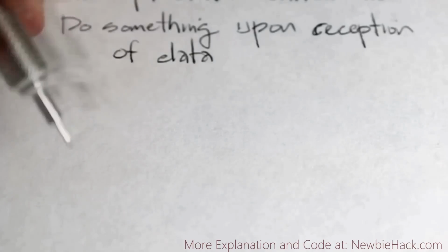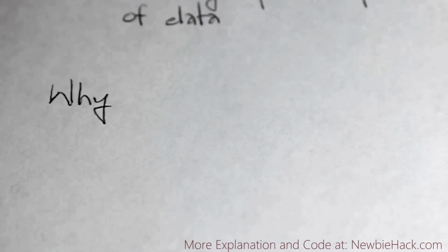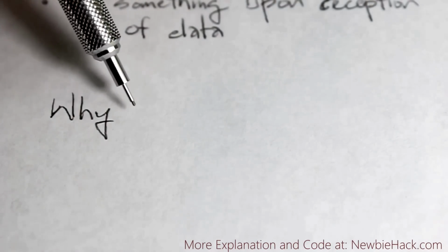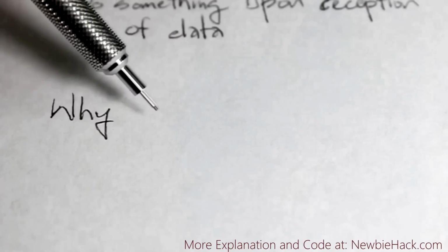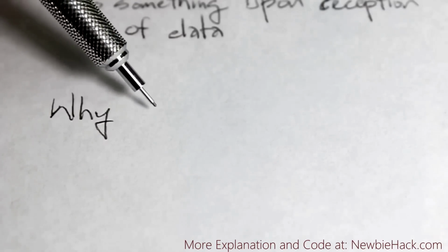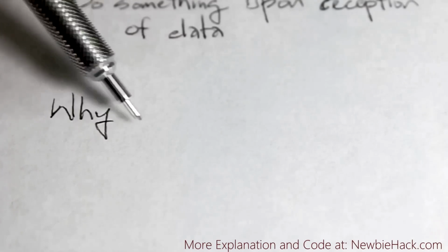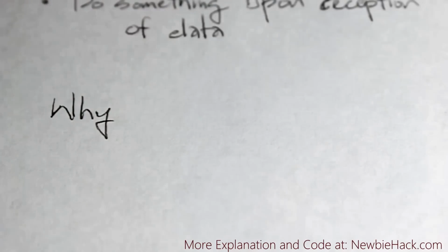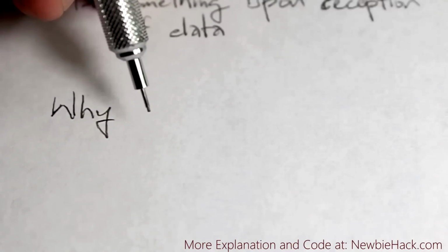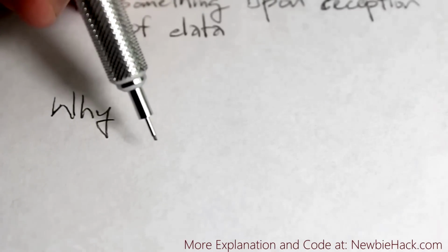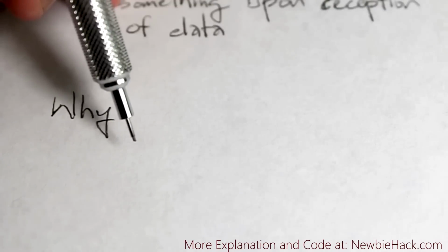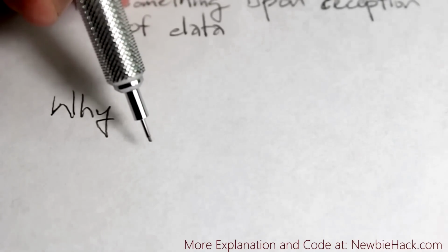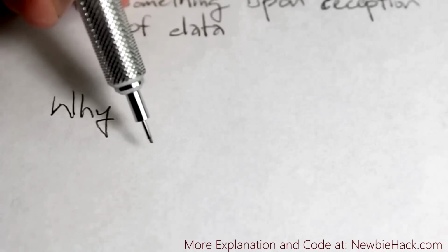Let's first discuss the external clock. Why do we need an external clock? In the previous UART videos, we connected two AVR microcontrollers together. And we were using a baud rate that was slow enough that the internal clock source was able to establish a communication that had less than 1% or an acceptable percent of an error rate. Communicating with a computer, you may not have the option depending on the application. So we need to find a crystal or a clock source that has a frequency that is acceptable to baud rates and that will be able to communicate with an error rate that's acceptable.